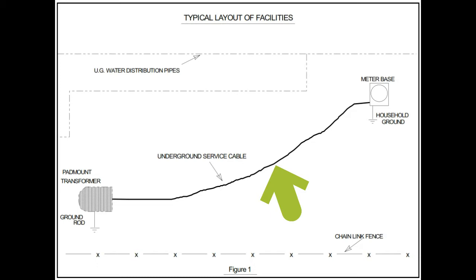In other words, we go beyond the halfway mark between the transformer and the service in an effort to get into the fault zone. It is possible that if you stop short of the halfway mark that you will get your higher readings as you move toward the transformer, because remember, most all of the current lines leaving the fault are flowing to the neutral at the transformer, causing a concentration of voltage gradients at the transformer just as they are at the point of the fault. So we have to be a little careful of how we work the instrument and in interpreting what we have as indications.